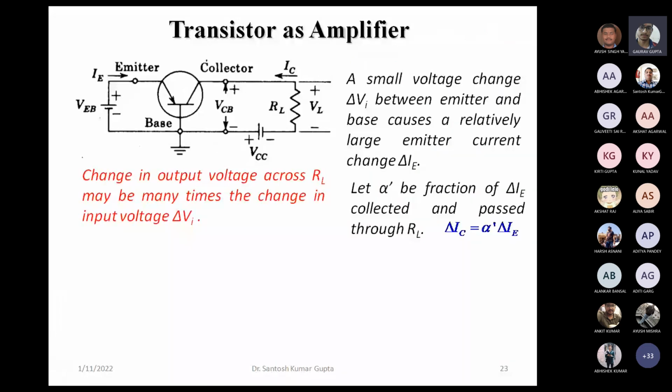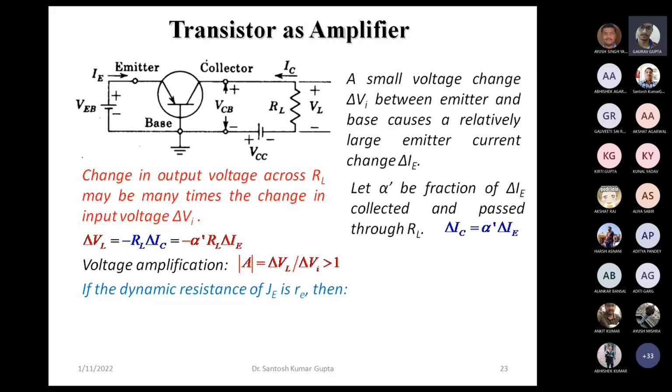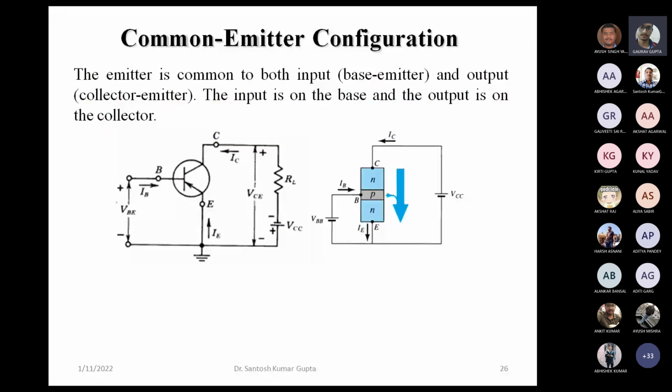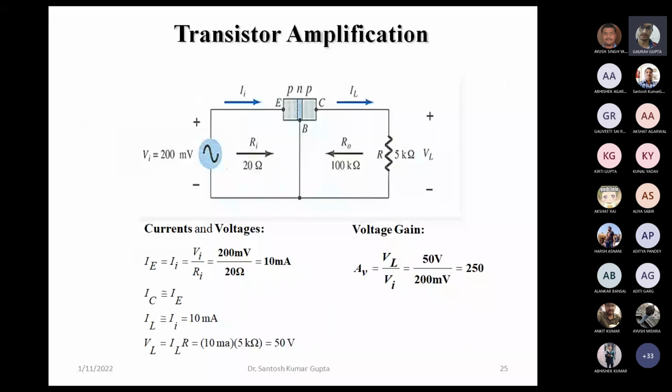The transistor amplifier we have already seen in the last lecture. Before proceeding, let us look at a quantitative example, which gives a feeling of what kind of gain we may achieve out of this. Here the input current, for the common base, is IE and the output current is IC. We have seen that IC is almost equal to IE because alpha is almost equal to 1.